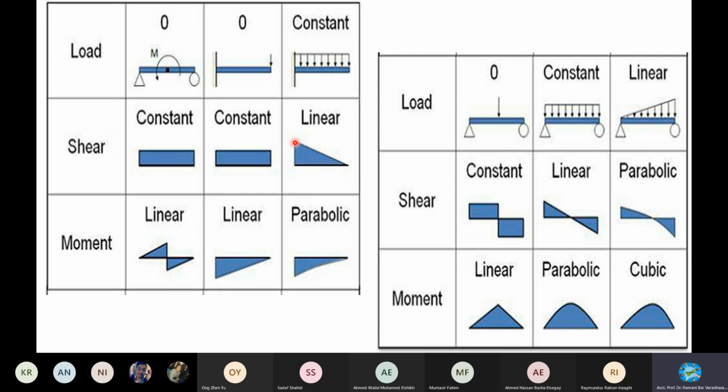You have some value here, and then gradually increasing. It should be a cantilever, fixed here. It's a fixed end, with UDL acting on it. Because it's fixed, there is a reaction. That's why you're plotting some value here.